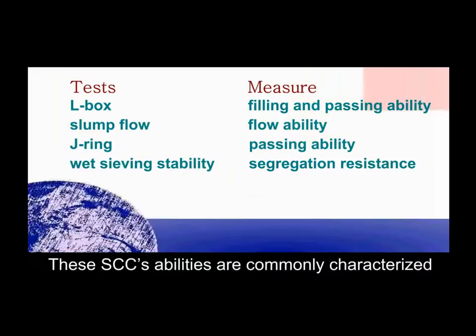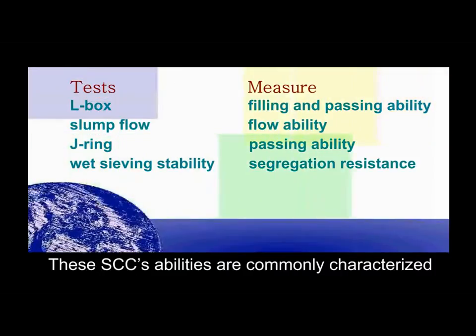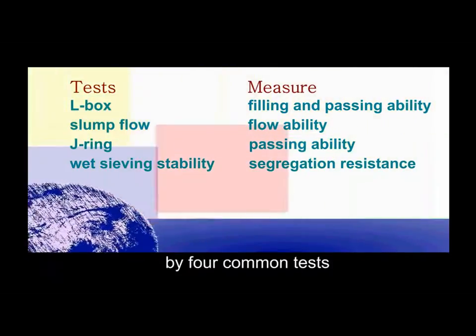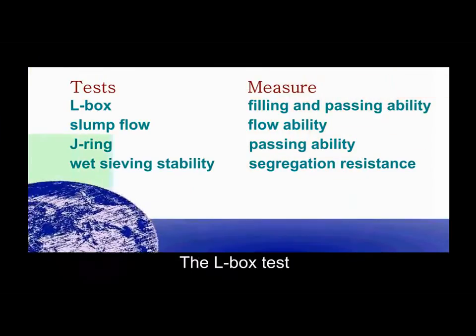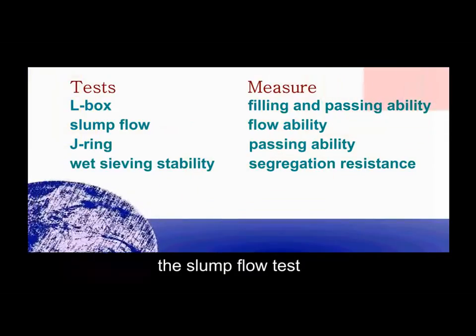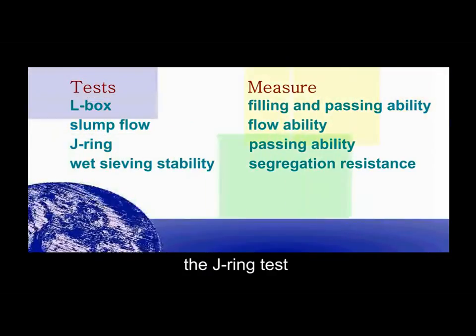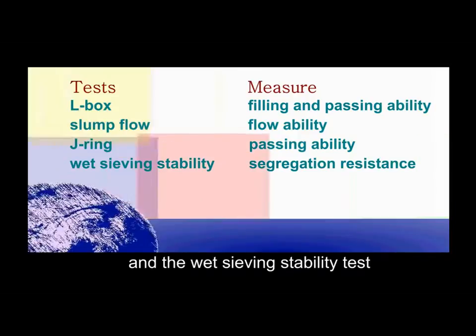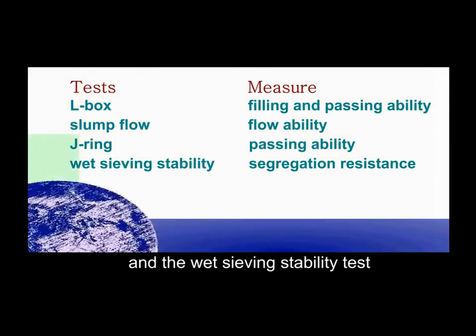These SCC's abilities are commonly characterized by 4 common tests: the L-box test, the slump flow test, the J-ring test, and the wet sieving stabilities test.